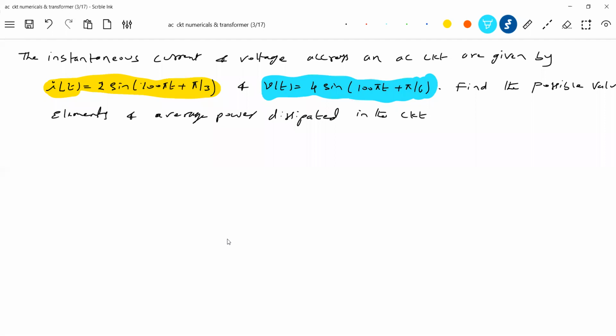From that we'll get the impedance Z. And after that, do we know omega? Omega is here 100 pi. And what about this? Is it an RC or RL circuit? Find the possible values. RC, so current leads the voltage. Current leads the applied voltage. So therefore it must be an RC circuit. Possible values is telling. Sir, I'll assume RLC. Then a little bit further information is needed. So therefore the circuit must be